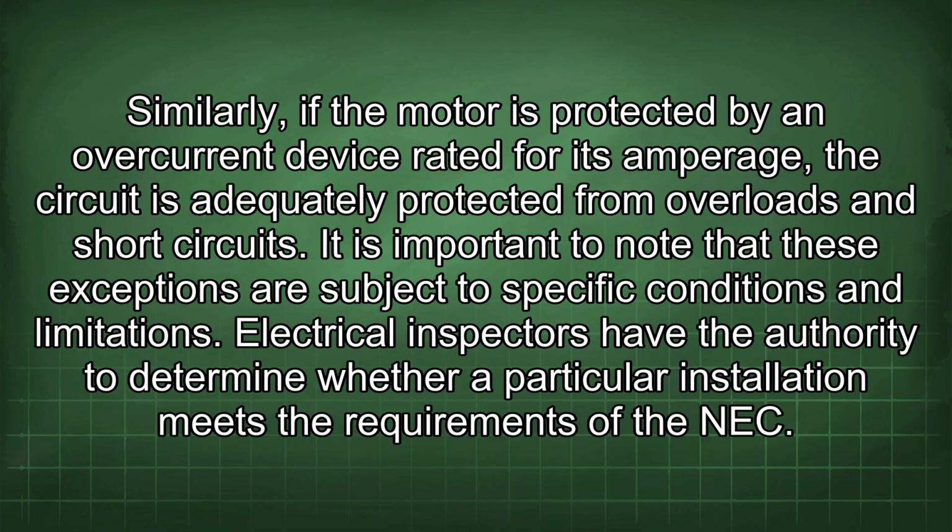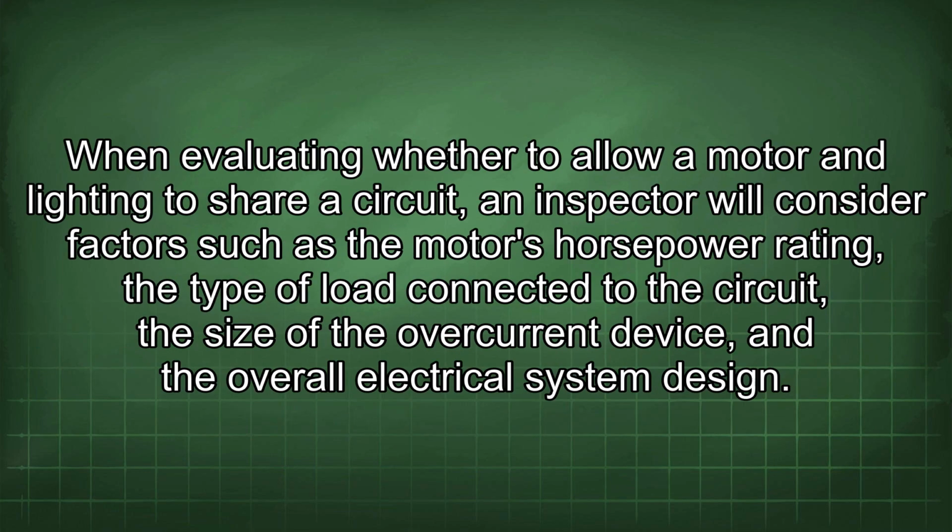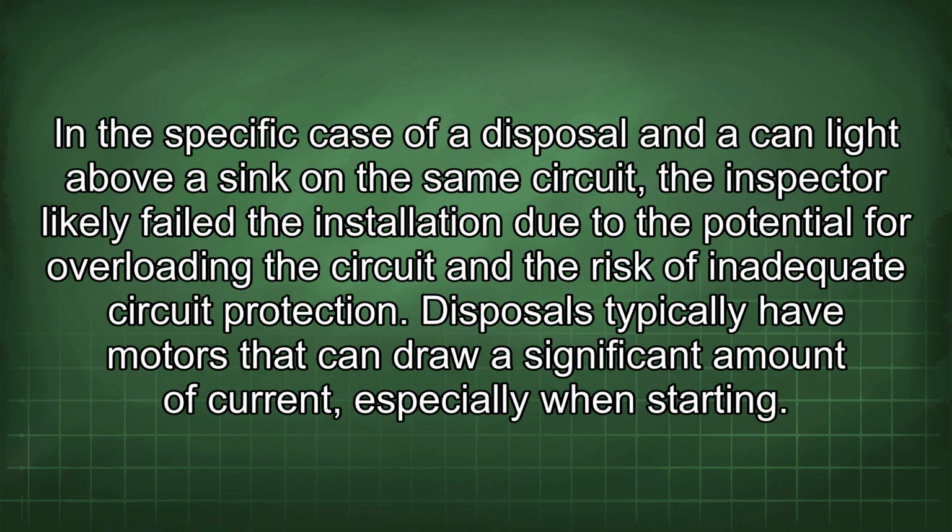Electrical inspectors have the authority to determine whether a particular installation meets the requirements of the NEC. When evaluating whether to allow a motor and lighting to share a circuit, an inspector will consider factors such as the motor's horsepower rating, the type of load connected to the circuit, the size of the overcurrent device, and the overall electrical system design. In the specific case of a disposal and a can light above a sink on the